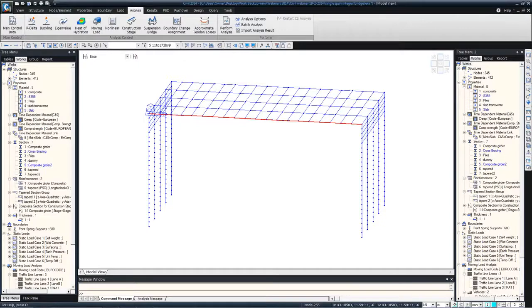There is another question, about the vehicle load for the case of special vehicles where we have straddling. The lane width is say 3.6 meters and the wheel spacing is 2 meters. So actually for the straddling vehicles, if you specify 2 lanes between which the vehicle will straddle, internally the software creates multiple lanes between those 2 lanes and places the vehicle on different lanes with the 2 meter spacing, and then gives you the worst effect.